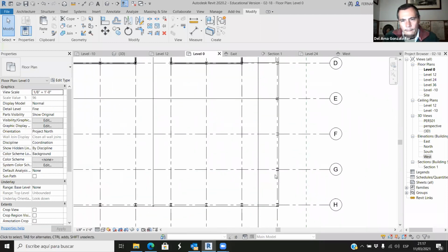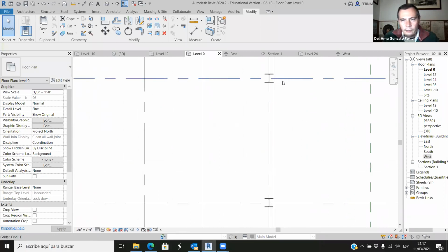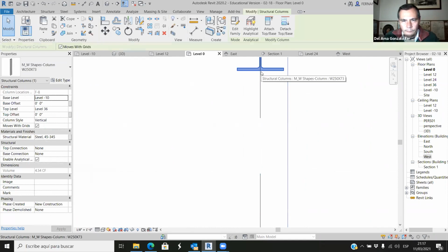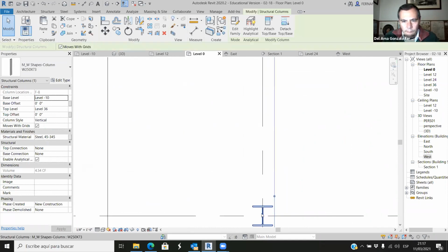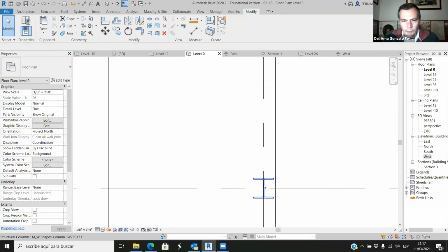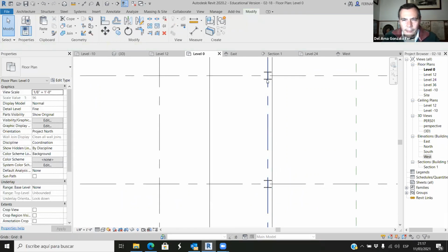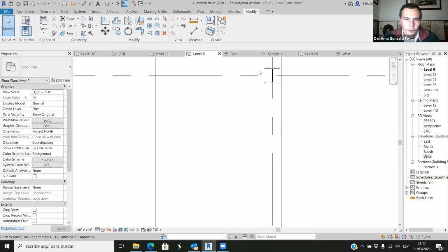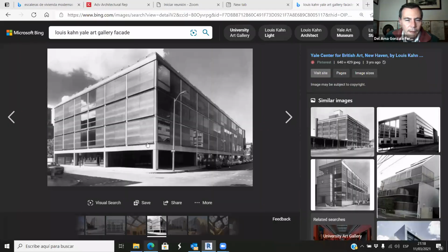Okay, so here we have the structural elements, and the wall is going to start here and end there. I don't want to hide the structure looking from outside, but looking from inside, I have to hide it because otherwise there will be a terrible thermal breach here. Okay, so that's the challenge. I want to do something like this, but without thermal breaches.